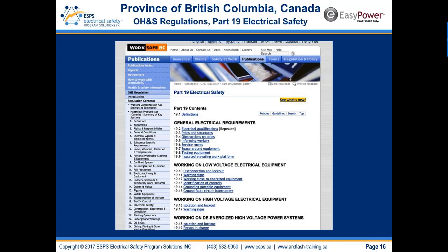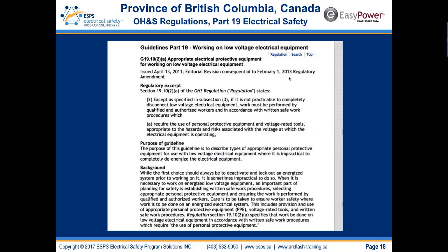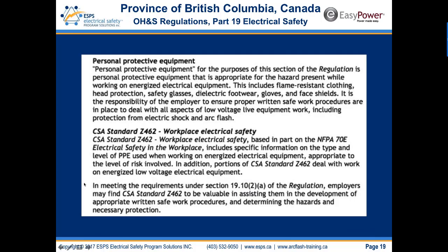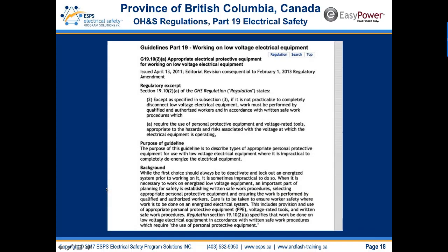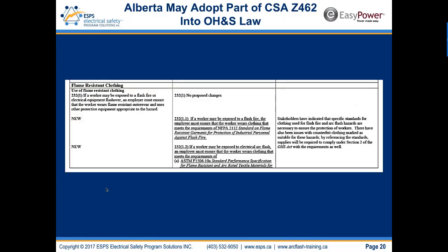Unfortunately, well, fortunately, it focuses on shock, but it doesn't provide a lot of guidance on arc flash. They do have guidelines in Canada for some of the provinces on the regulations. They give you some additional information. So in British Columbia, they actually do advise an employer to informally review the Z462 standard, but they use the language "may find CSA Z462 to be valuable." It's not formally adopted into law. So again, a little bit of information on British Columbia.